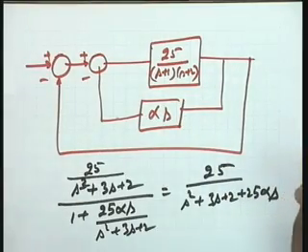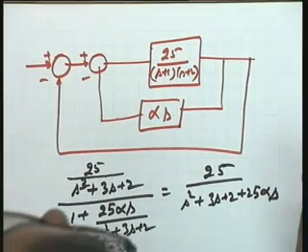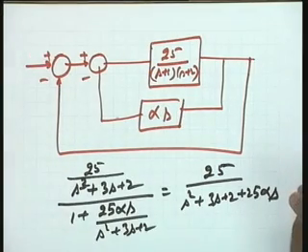I need your attention on this point please: what is the root locus gain K? I am trying to explain to you. In the earlier example it was purely an amplifier gain, and the poles and zeros of F(s) were the same as the poles and zeros of the open loop transfer function of the given system. Now I have taken a tachometric feedback, and resolving the minor feedback loop, I get this as the forward path transfer function.